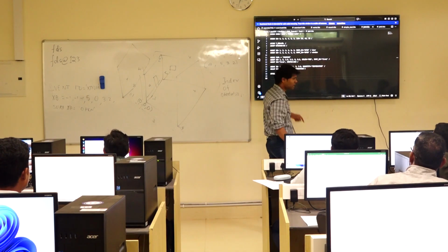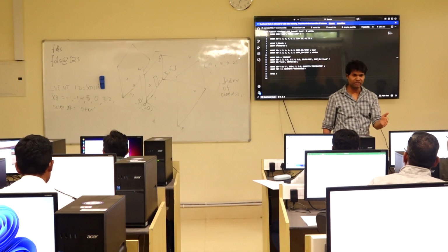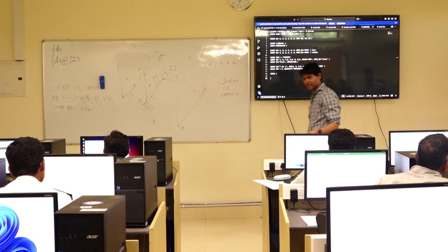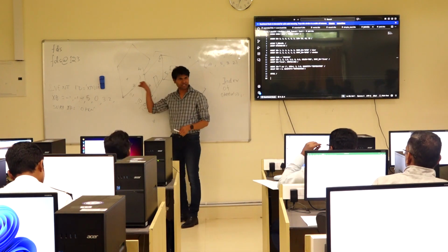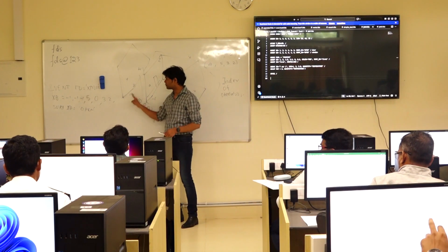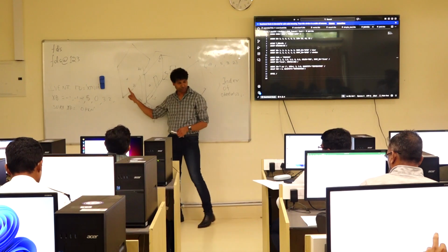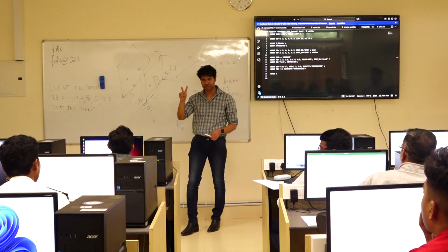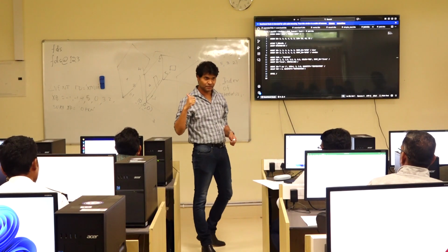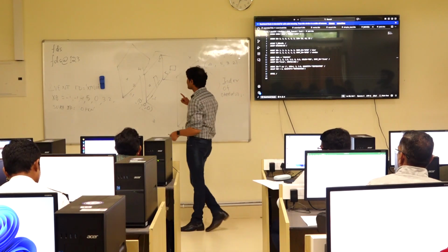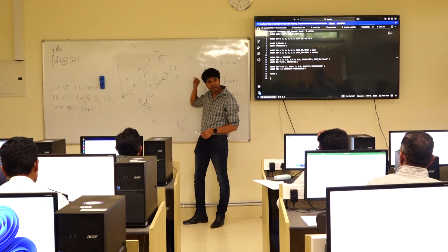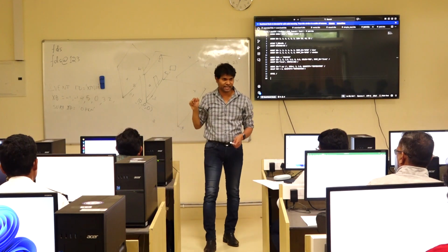And then do the exact same thing. SURF_ID is equal to OPEN. IOR should be -2. Okay? Because you need to tell FDS that the combustion products are going to go into the negative y direction. This is x, this is y, and this is z. And 2 is for y. Okay? 1 is for x, 2 is for y. Similarly, for y max, it will be +2. So the products are going to go in the positive y direction. Are you with me?